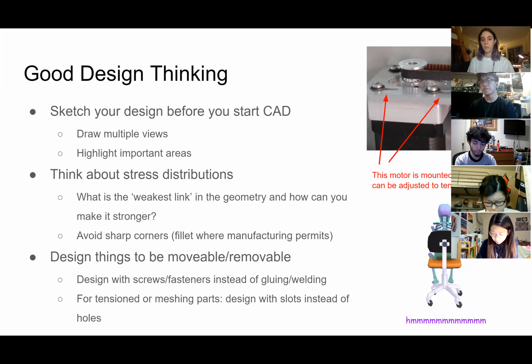I think the most important thing is to be able to design things to be accessible. Modular designs are really helpful in an assembly. For example, if you had a robotic arm that had 5 fingers, and you wanted to fix the pinky, it'd be a lot more helpful to just take the pinky off individually, as opposed to taking off all 5 fingers beforehand.